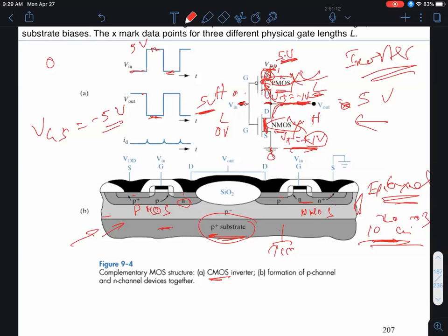After you do that, I have to make my billions of transistors on this piece of silicon, right? Maybe an inch by an inch, right? So you have to make sure that adjacent transistors are suitably electrically isolated. And essentially the way you get that is by growing a very, very thick oxide in these isolation regions, okay? Now, I'm not going to go into the details of how that is done.